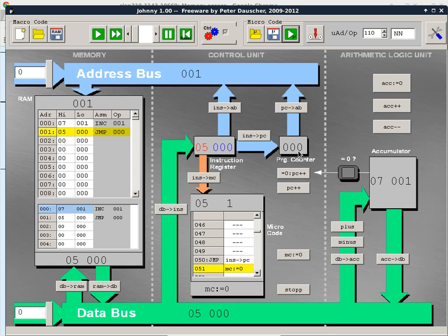So now the program counter is reset back to 0, and then we reset the MC counter, or the microcode counter, back to location 0. So we are going back to location 0 to perform this operation. Now this operation is going to do something funny. Okay, so without actually microcode stepping the entire thing, what is this instruction going to do? Jump. Is it going to increase the low and jump? Exactly. It's going to increase the low of jump. So jump will now point to itself.